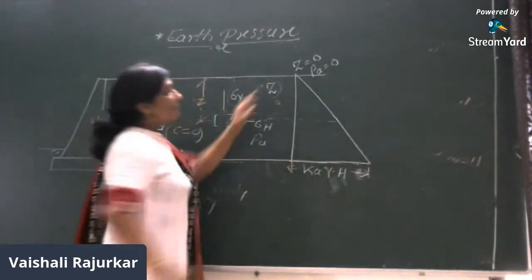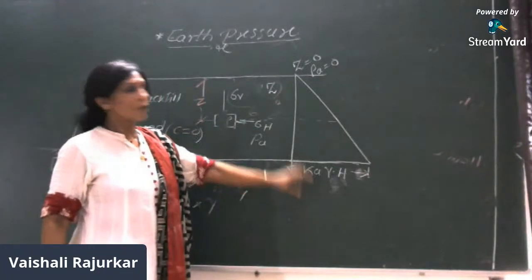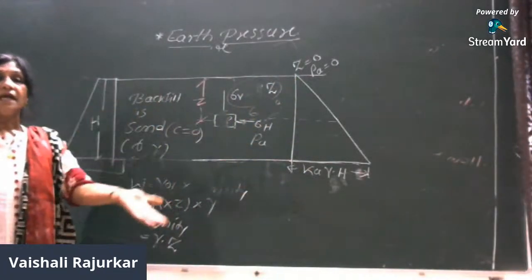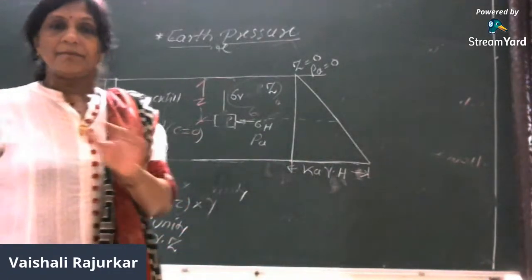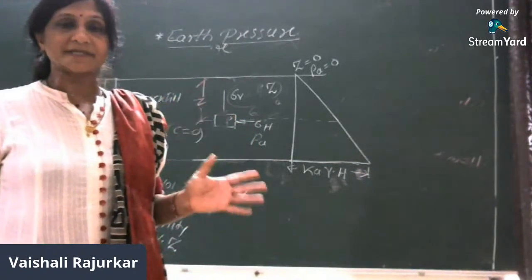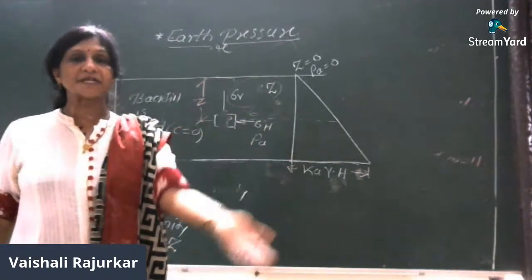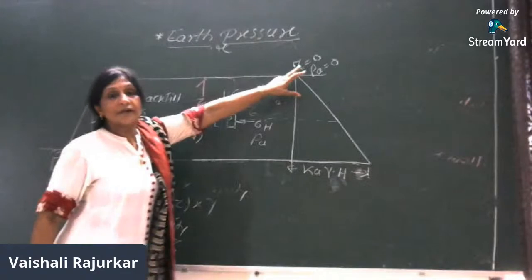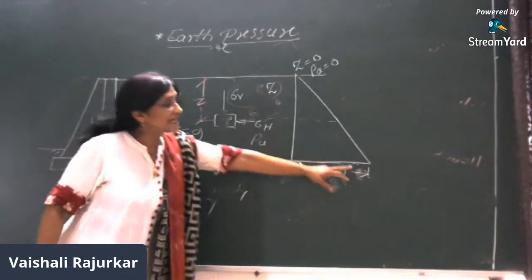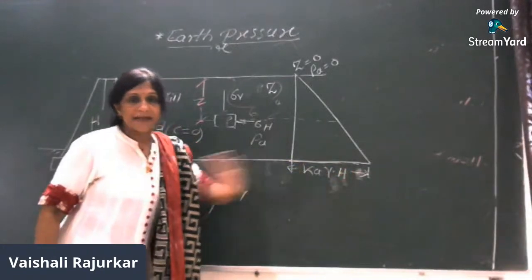So this is the maximum pressure at the bottom because sandy soil exerts the pressure immediately, because it cannot stand unsupported. Without support, it cannot stand. Therefore, it exerts the pressure over the retaining wall, and therefore, when Z is equal to 0, the pressure is 0. When Z is equal to H, pressure is maximum.